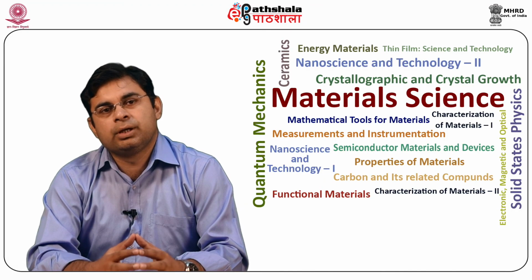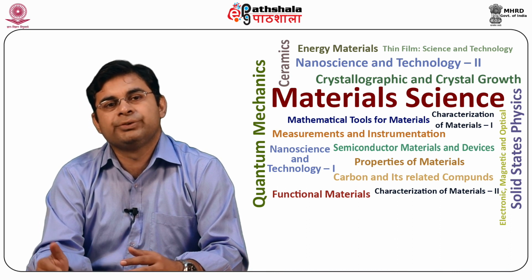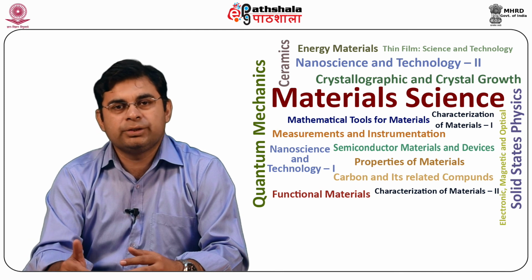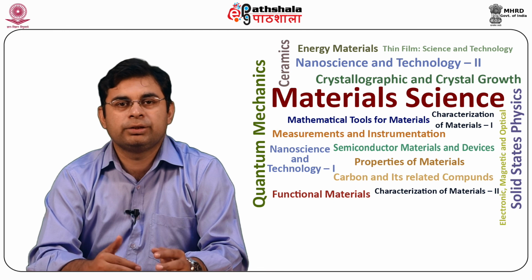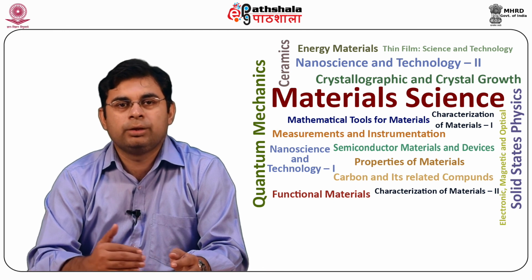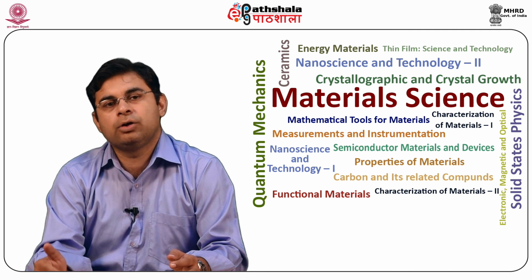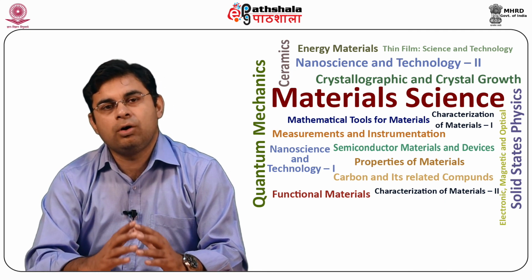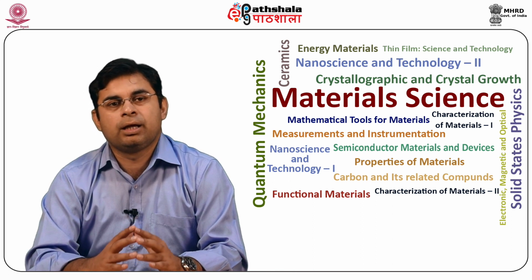Quartz crystals can also be used as mass to frequency converters. A crystal controlled by an electronic oscillator has a thin quartz plate. The frequency of electrical oscillations depends on the natural frequency of mechanical oscillation of the plate.